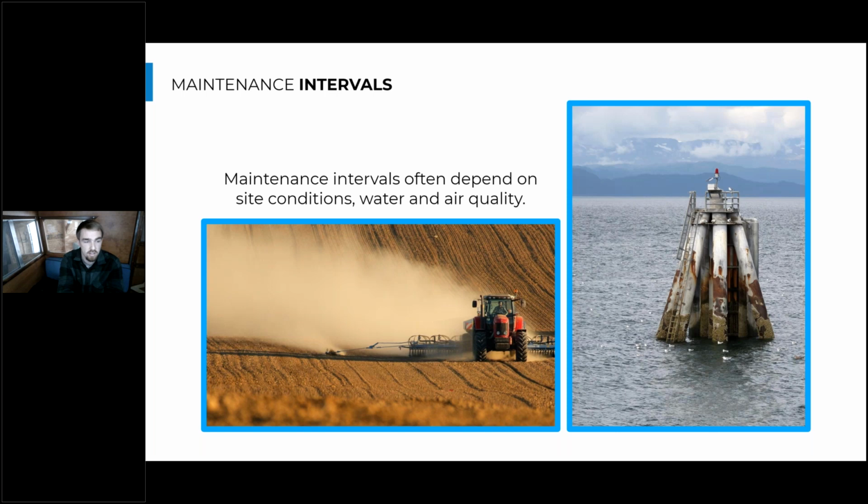But if there's plowing in the spring and in the fall, that additional dust in the air and any sediment in the air might really bog down those filters a lot more quickly than you'd anticipated if you were in a different environment where you don't have that agricultural background. As well as one site condition that's really important to mention, especially in Seattle, is in marine climates, you want to ensure that you're inspecting your air coils on your heat pump water heaters to look for any corrosion or anything like that due to air that's a lot more harsh to mechanical equipment.